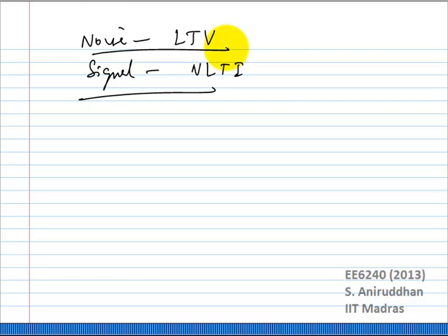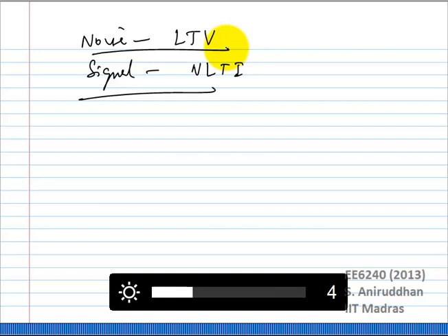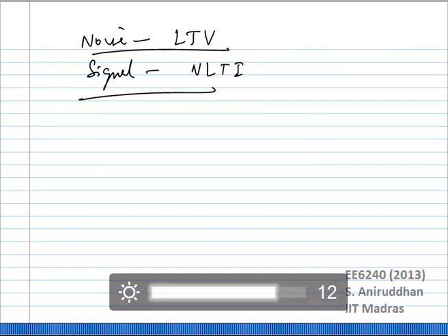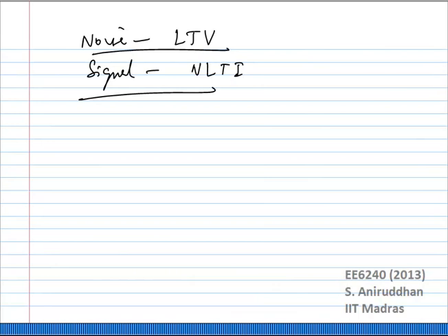If you take pairs of ports and look at the transfer functions between these, some of them are nonlinear but time invariant, and some are time variant. In the case of the VCO, let us look at the signal behavior. Do you expect some kind of time variant behavior, and if so, what kind? In the absence of noise and assuming that the circuit is perfectly symmetric, there is no need for any time variance analysis.